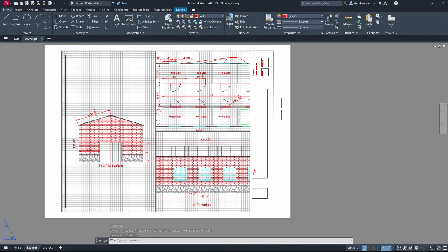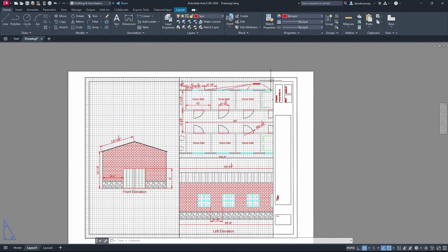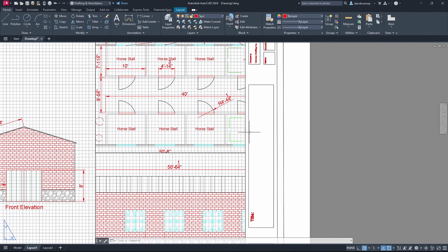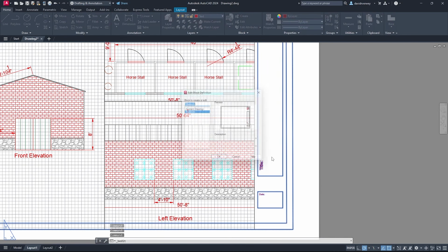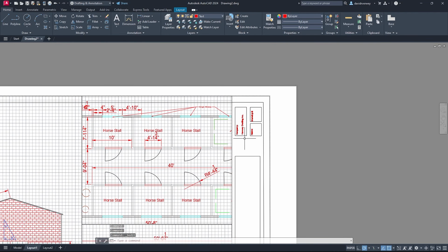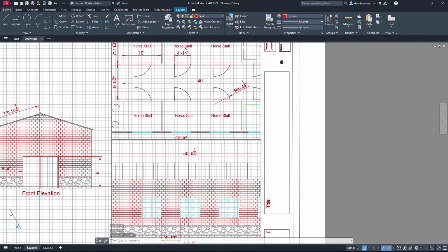And that's it. So one thing to note is when you have the double lines going around, you're going to want to shrink your viewports to match up with the inner line. If you don't do that, because I didn't go over that before, that's fine too. Then you can type in your text and everything, put in your title. You can edit your text in here, put in your title, put in your date, put in your name, drawing number, everything like that, and everything will be there.